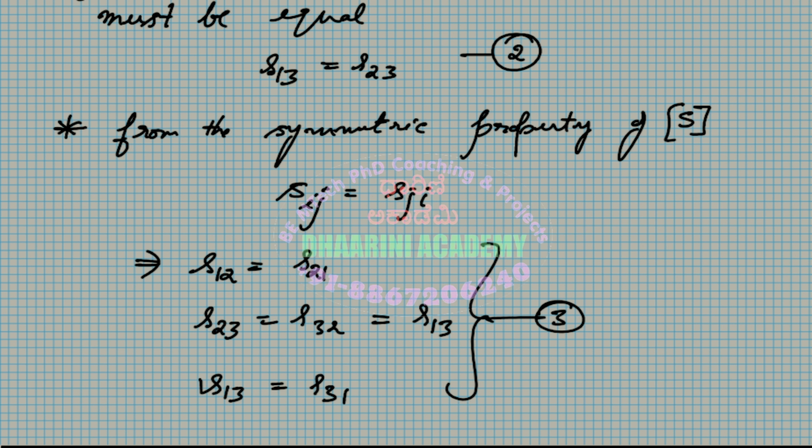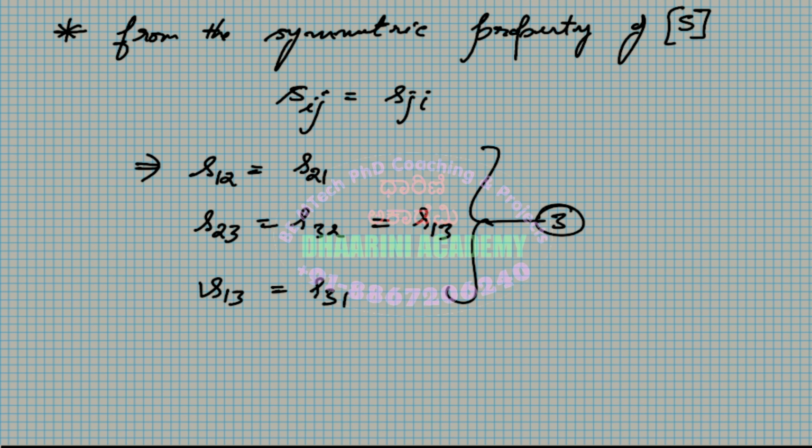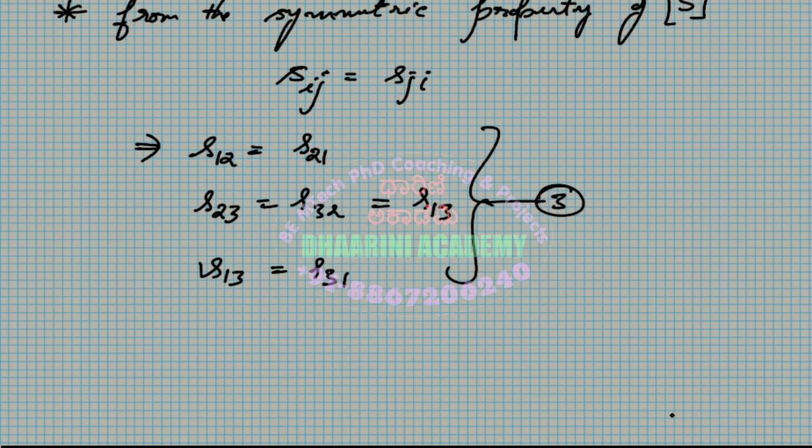I'll add another one. There is a very peculiar feature of this H plane T junction: it is a perfectly matched junction for the third port. With respect to port number 3, it is perfectly matched, in the sense of no reflection.